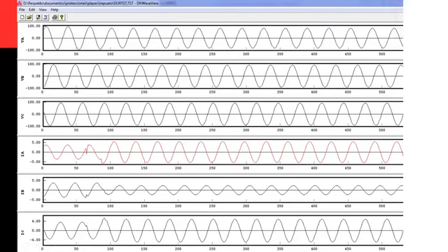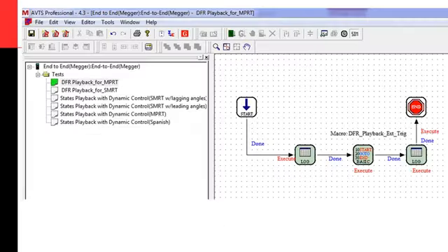For the purposes of end-to-end testing, what you need to know is that you have the ability to get a COMTRADE, then play it back either manually or synchronously using another tool that is built into the same software from Megger. And this essentially allows you to do the same that we did with the states playback. We can play back the fault into the relays at both ends of the line, or as many ends of the line as I have, at the same time.